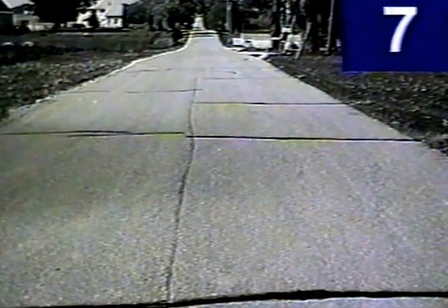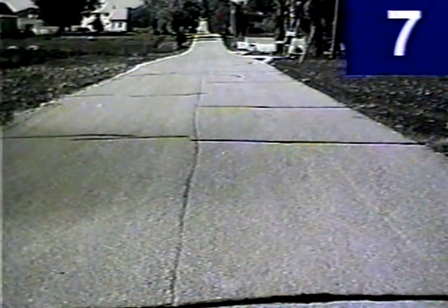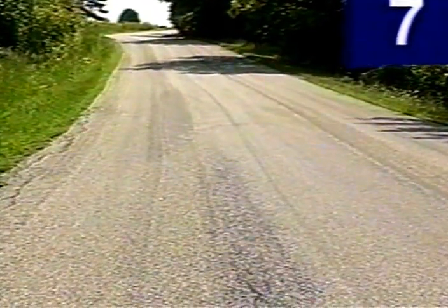Next, I'd like to move on and we'll discuss pavements that are rated a 7. Pavements that are rated a 7 are candidates for crack sealing. Here's an example of a pavement with transverse cracks. They've opened up enough to the extent that we should do some crack sealing early on in the life of the pavement. A good candidate for this kind of preventative maintenance. Here's another pavement that I would rate a 7. It's in good condition, and just some crack sealing would be in order.